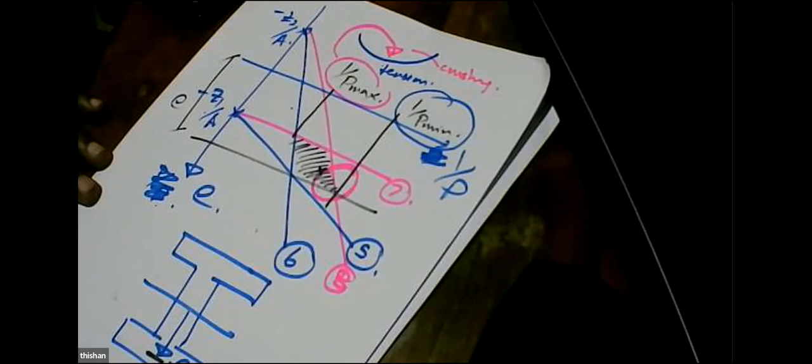But if we go for the maximum pre-stress, it's very expensive, because we have to create a massive pre-stress. But the problem with massive pre-stress is it's going to fail in compression. You will get a sudden failure of the beam. So we always like to use the minimum pre-stress. Is that clear?